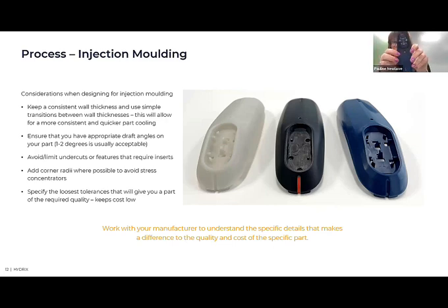one side of that undercut is molded by one side of the mold, and the top side of that feature is molded by the top side of the mold. And that means you can still have, for example, here we had to have some protrusions to hold our buttons in place, but we still managed to get that done in just a two-part mold by having cutouts that allowed us to mold the features in either side of the mold.